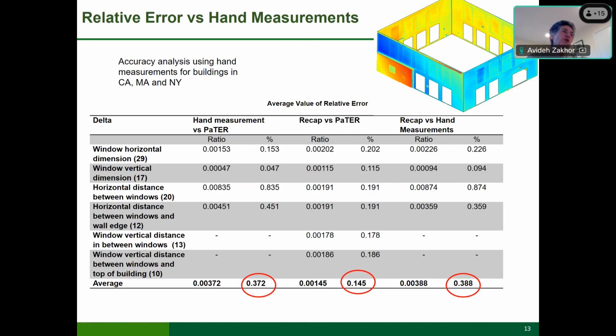They also agree with us that if you go to Recap and do the measurements and repeat that 4 times and make sure you get the same measurement over and over again, then that is pretty accurate. So it's generally agreed upon that multiple measurements in Recap is accurate, but that's not practical, and it's also not repeatable. If you want to get 4 consistent measurements with Recap, you have to try at least 10 or 20 times to get it. Each time you get a different number.